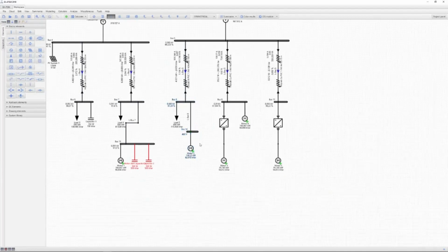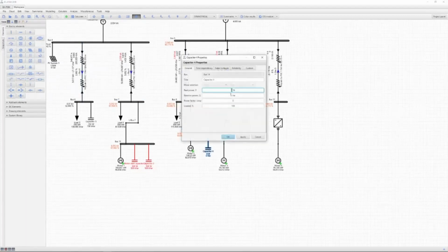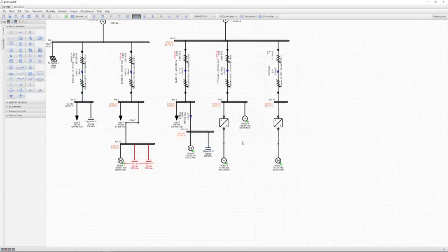To check again, we're gonna do the motor analysis. So we can see here 991 kilowatts are generated, and here is 35. So at the moment I'm gonna add a capacitor battery here. We're gonna use tab as I mentioned before. I'm gonna add approximately 200 kilowatts, and check if the situation gets better.